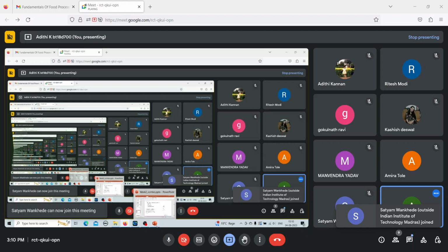In the previous case, tau is the same for both: tau of spring is equal to tau of dashpot equal to tau, but strains are summative. Here it's the other way around. For the Kelvin model, strains are the same, and stresses are summed up.